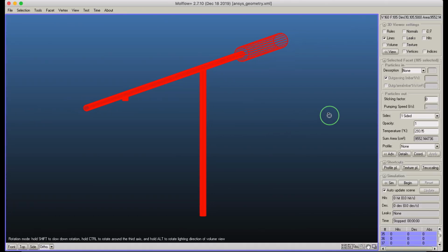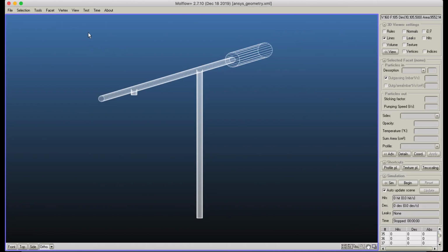So going back to Molflow, you have two ways to define an outgassing. When you click on a facet, like a single facet, you have to choose the directional distribution. Now, most vacuum systems, when you inject gas or when it's coming from the wall, it's obeying the Lambertian or cosine distribution. So most of the cases, you would be using the cosine distribution.